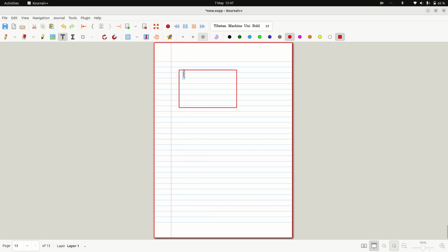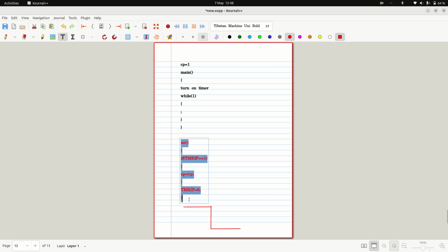So how does the timer start counting? Initially 0, 1, 2. When it reaches 255, once it is 255, then it rolls over to 0. Now increment to 256, is it possible? No. So what will happen when it reaches 255? Then it rolls over to 0. Control comes to the ISR. So when control comes to the ISR, toggling happens. CP equals to 0.